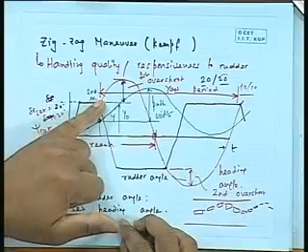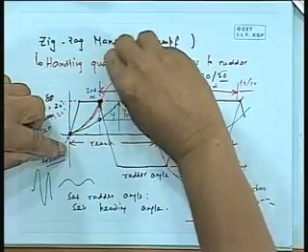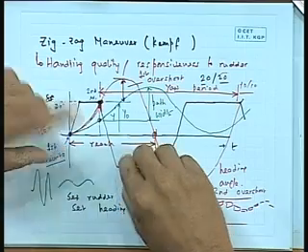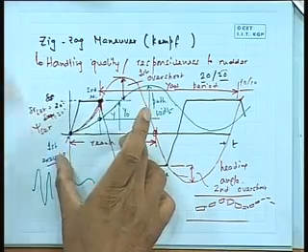See, if it responds very fast with rudder, I mean the moment you give a rudder, there is a force there. It would actually go down here, it will want to turn, but it has already gone so much, it will go like that and then turn. So typically you will find that if rudder is very effective, then overshoot goes up, the time comes down, because you are very fast, it is turning.